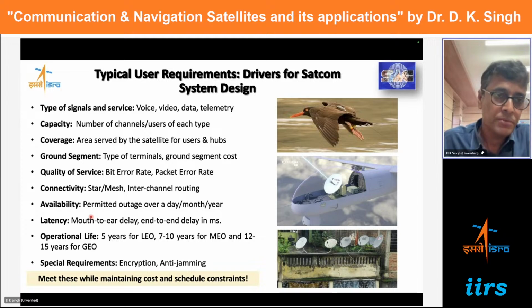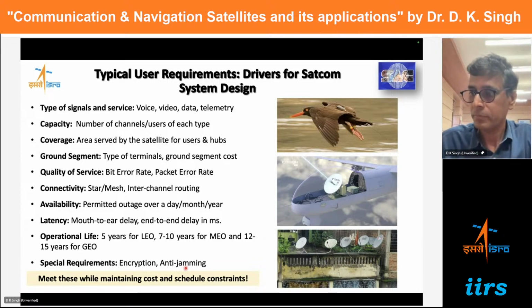Then the most important thing is the availability of the system. What is the downtime which is acceptable to you? Then latency. So sometimes the latency becomes very important when you are talking about very high data rate communication, or when you talk about the voice communication. So in such cases, the low Earth orbit satellites which are near to Earth, which are offering some few tens of milliseconds of latency, they are preferred. Then of course operational life, then certain special requirements like whether you want encryption or jamming, security, and so on.